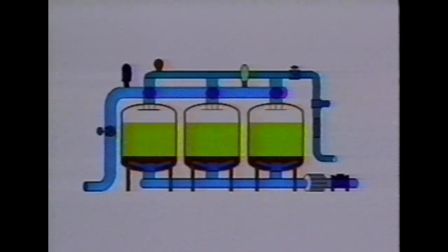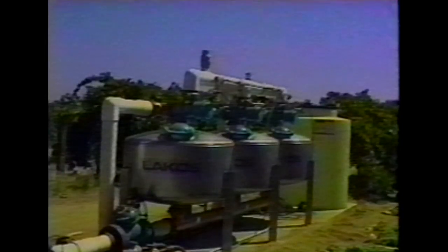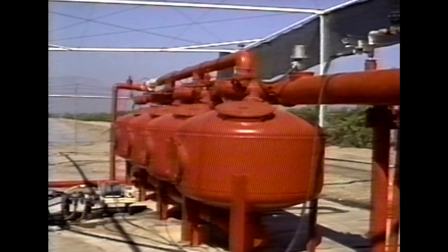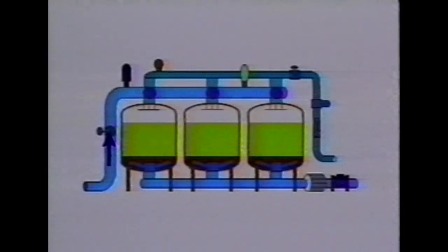A minimum of 2 tanks are required so that clean water is always available for backflushing. At least 3 tanks are recommended. Tanks typically come in 12 to 48-inch diameters. For very large flow rates, many 48-inch tanks will be installed in parallel. Each tank has an equal amount of water flowing through it. For a 3-tank system during normal filtration, 1/3 of the water will flow through each tank.